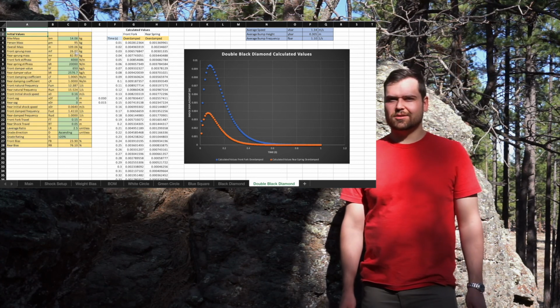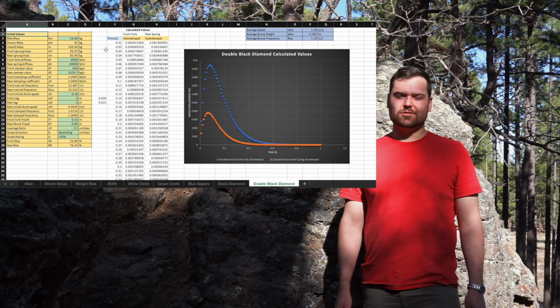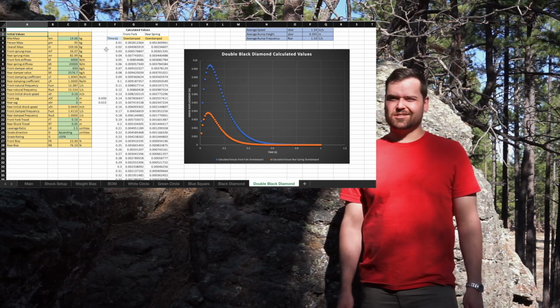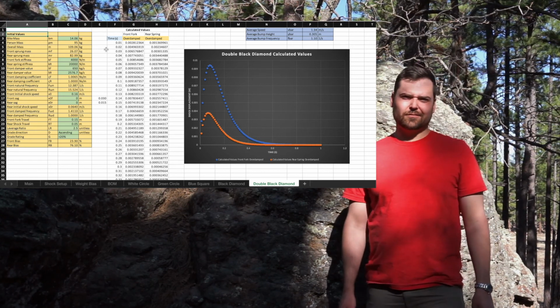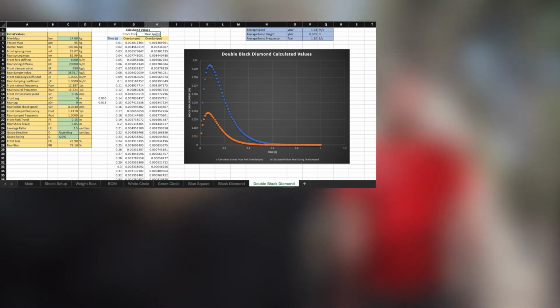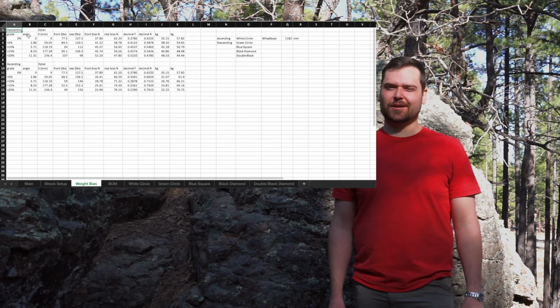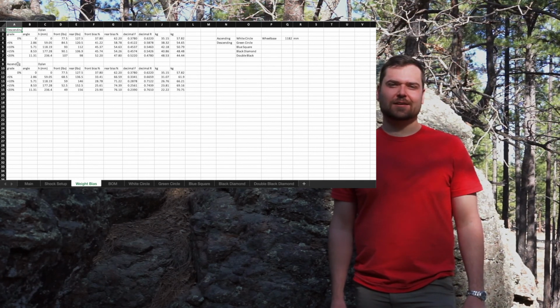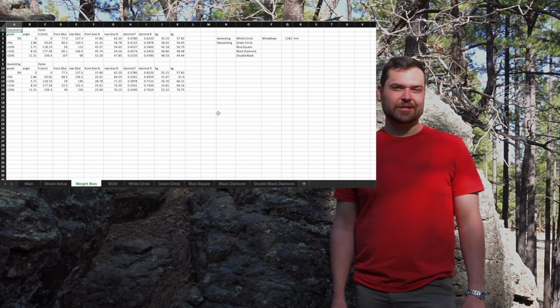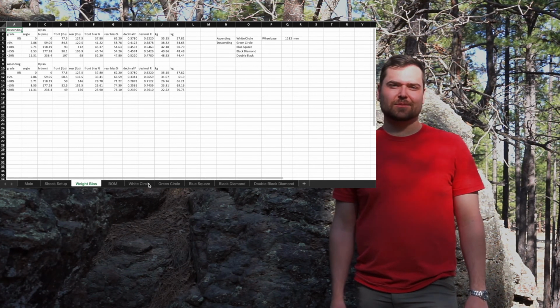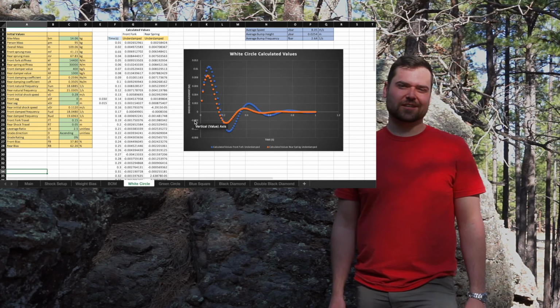It also calculates or lists input values for our driving spring mass dash pot differential equation, which is calculated for the front fork and rear shock independently. Weight bias data are incorporated as a trail grade and ascending versus descending distinctions. The graph generated for each trail type is displacement at 100 Hz over a 1 second interval.